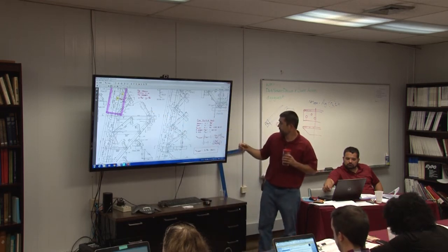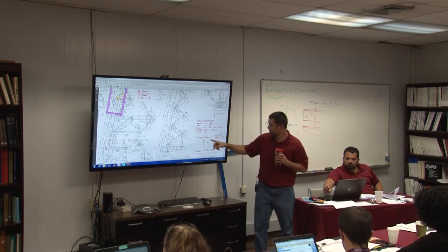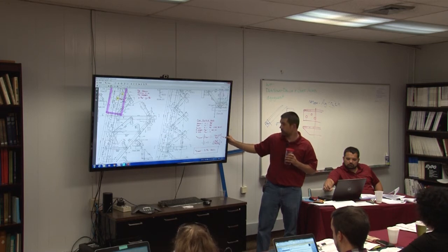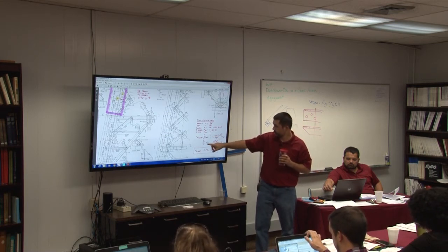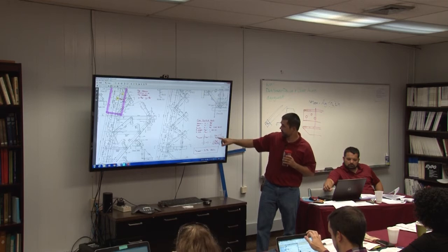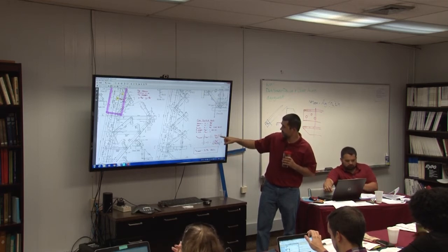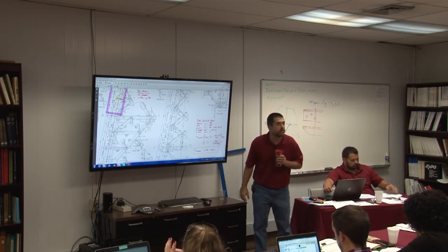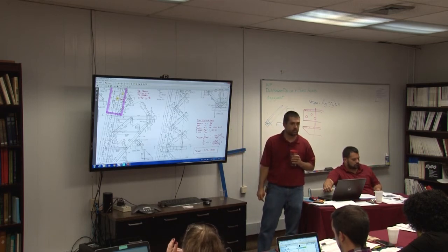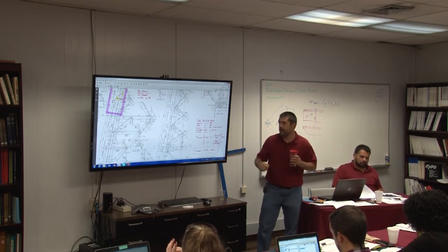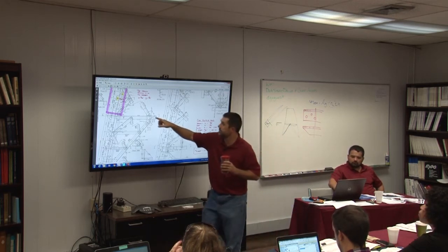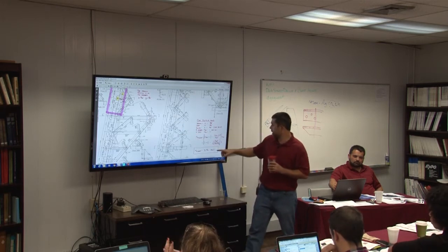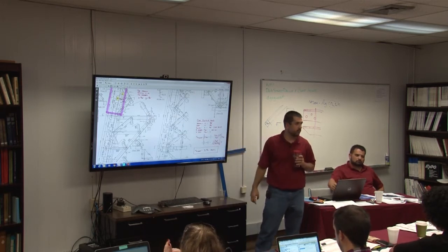So the number of legs. I can take the general equation that I provided before, and I'm just going to basically double it because I'm going to multiply it by the number of legs. So the number of staggers plus 1, and then I plug in everything else into this equation: the number of staggers, the S, the G, the H. If I do all of that, what spills out is 3.96 holes. You could have just put 4. And does that make sense? Absolutely, because these 2 holes are almost perfectly aligned. If they were perfectly aligned and my stagger was 0, then this whole thing turns into 4.